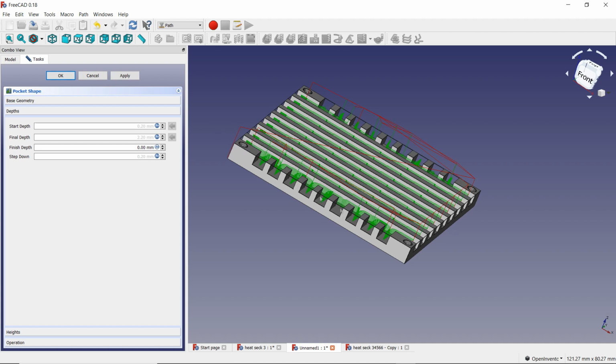The top of the part was my 0 point. Now it will move up from that and then move over, and then it will start cutting down. But as it's cutting down, it wouldn't actually be cutting the part, it would be cutting air. The tool wouldn't be doing any work. It would just be sitting there cutting out the air, and that's it. It wouldn't be cutting anything, which isn't good for me.